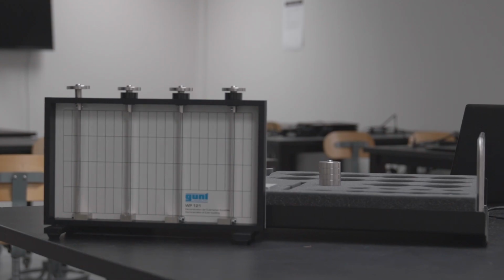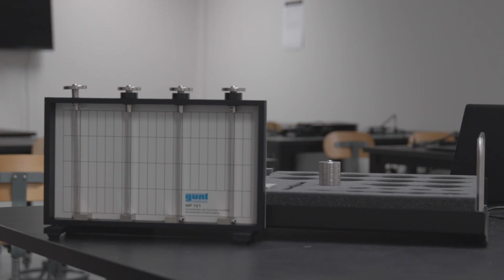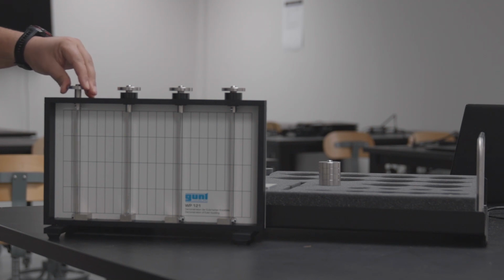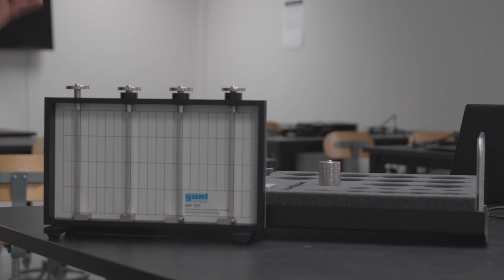When you look at these 4 columns, you might not see that much of a difference, but the difference is not in the column itself. The difference is in the supports. As you can see, we have a free support up here, right? What is a free support? It essentially means that there is no constraint in the movement of that end of the column. It can rotate, it can move, it can have displacement, like translational movement and rotation. So this is the free end of the column.